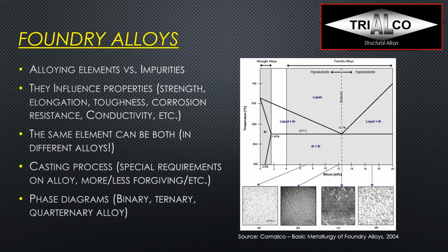To the right, in the same triangle, we find liquid and silicon that solidifies first. If we fall below the 577C line, where the eutectic liquid is all frozen, we find aluminum and silicon, and this time now it's all solid.